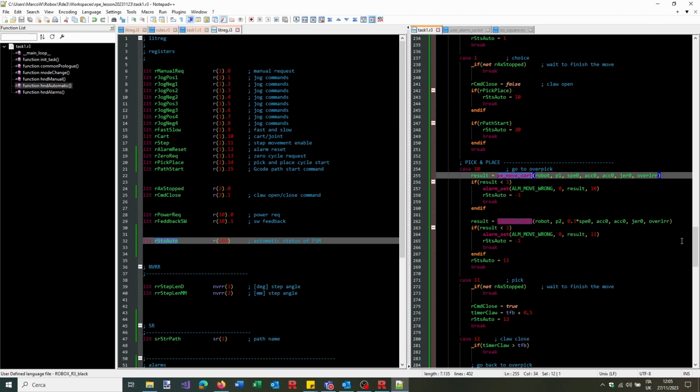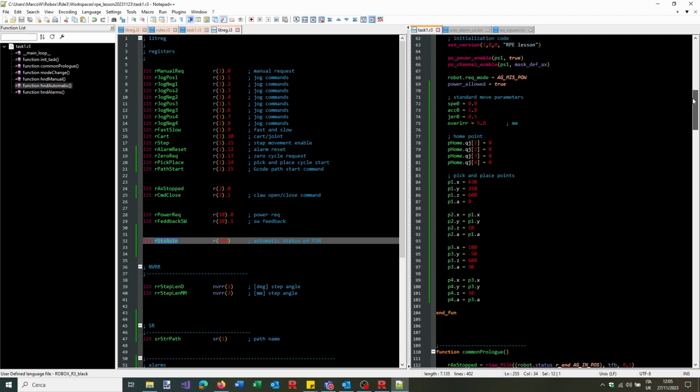Yes, of course, I did it wrong. That's due to my initial point. Yeah, I cannot set the home like this. My fault. Of course, since it is a SCARA robot, asking 00 means to have the arm completely open, so completely extended, and that's not a beautiful point. In fact, as we said before, this is exactly the kind of thing that we should never do. Then I know that the speed may be somehow fast, so we reduce it. We make it 0.8. All right.